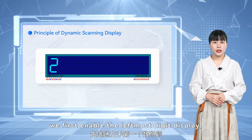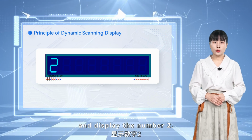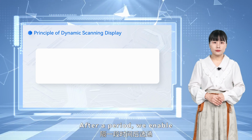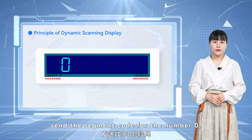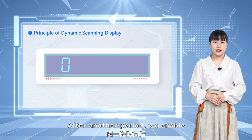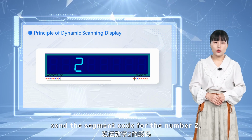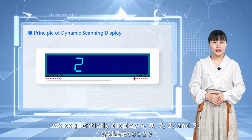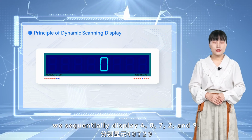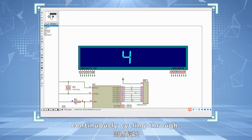Controlled by the program, we first enable the leftmost digit display, send the segment code for the number 2, and display the number 2. After a period, we enable the second display from the left, send the segment code for the number 0, and display the number 0. After another period, we enable the third display from the left, send the segment code for the number 2, and display the number 2. Following this pattern, we sequentially display 4, 0, 7, 2, and 9. Then we start the display process over again, continuously cycling through.